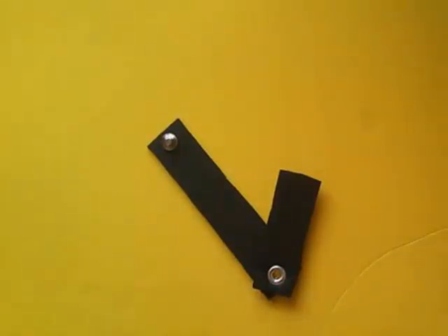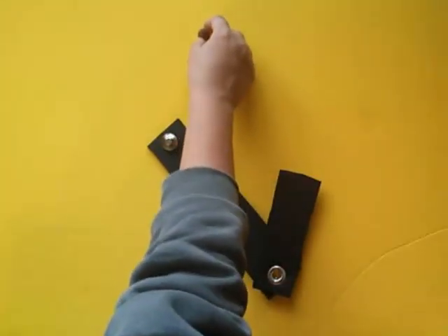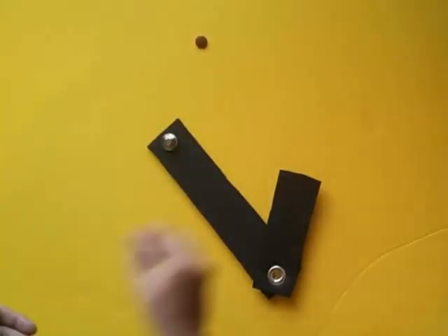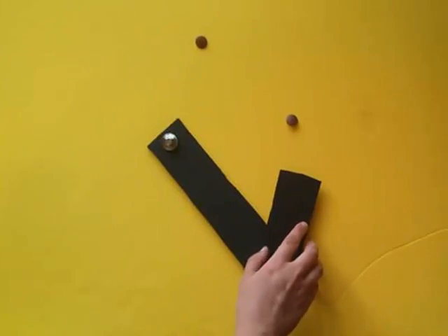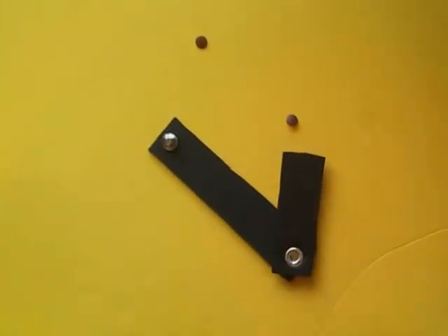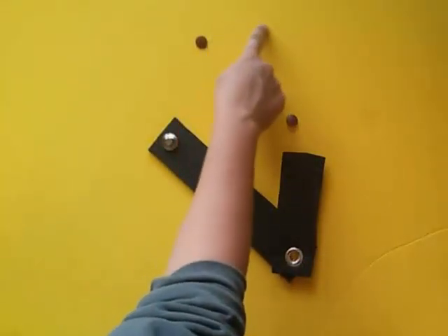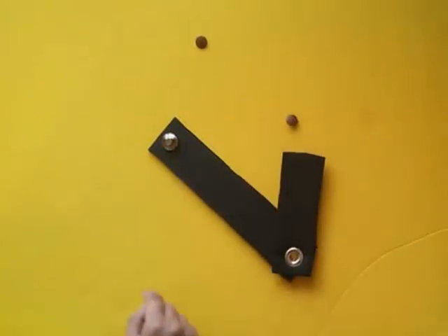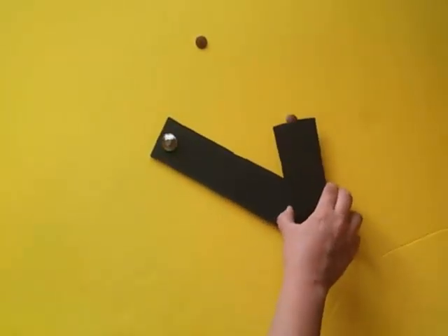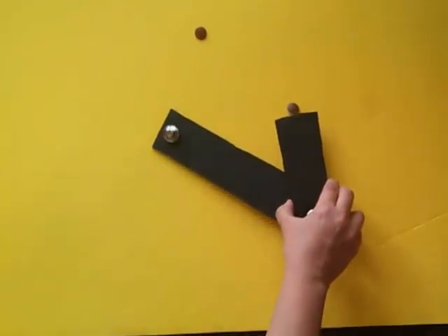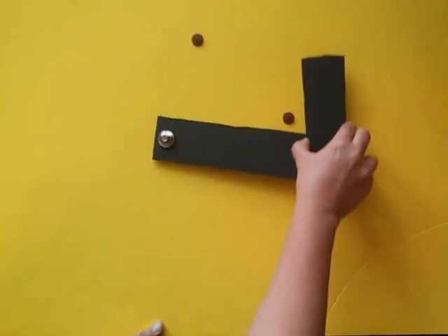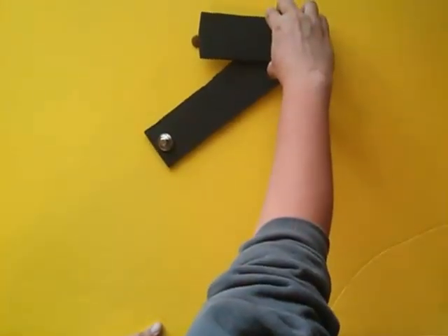In the simple path planning problem that we saw previously, we had a situation where we had a target pick point and a target place point, or in other words, 2 target points that we wanted the end effector to move between. And we also had a target path that we wanted the end effector to use, for example, a half circle between these 2 points. And we learned how to move the end effector from one point to the other through the path that we specify.